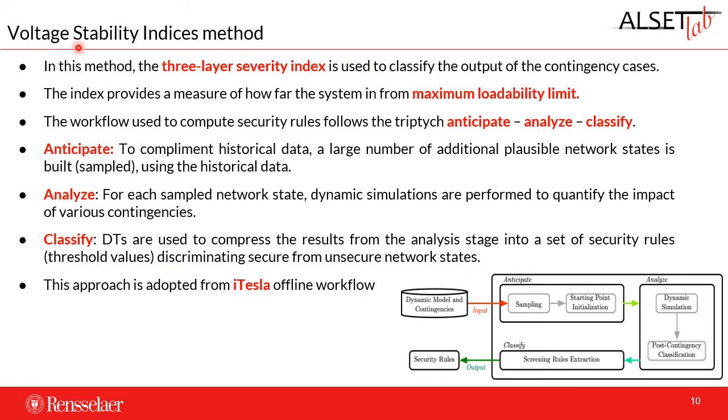So the first method is the so-called voltage stability indices method, and here we use a 3-layer severity index that allows us to classify the output from dynamic simulations of different contingencies. So the index actually will provide us a measure of how far the system is from the maximum loadability limit. The workflow used to compute the security rules follows the triptych anticipate, analyze, and classify, which is depicted in the figure below. We have a dynamic model and a specification of the simulation scenarios for each contingency.